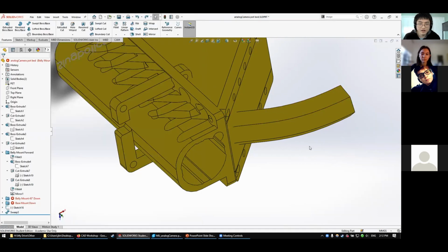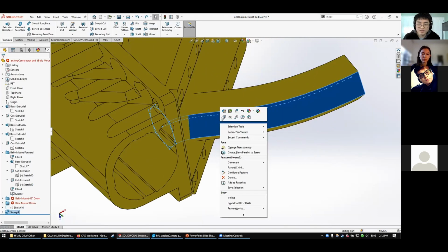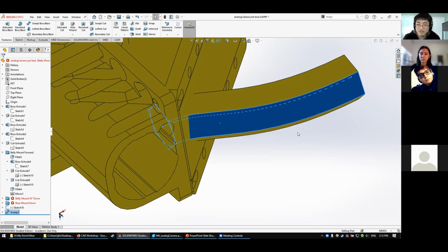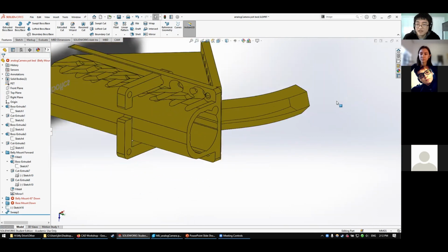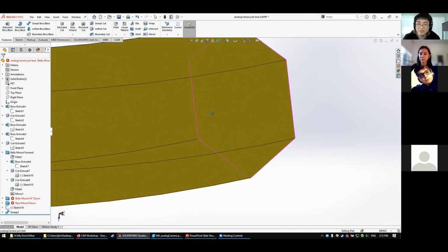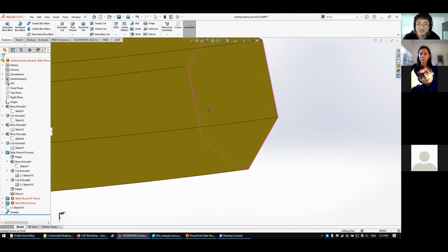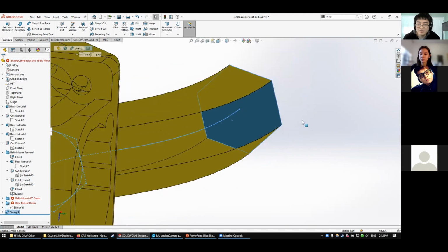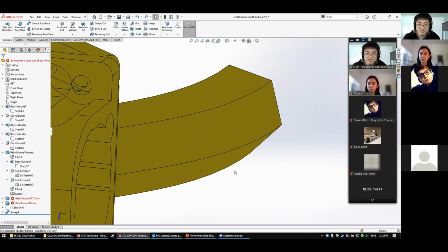And those two buttons are in the right-click menu, and you'll see here, suppress, and here is the hide button, the eye with the cross through it, and transparency is down here. You'll see here it says face, change transparency. So you'll be making this face transparent, and you can see inside the face. So now I can see inside this hexagonal, not prism, but shape. So that is the change transparency.